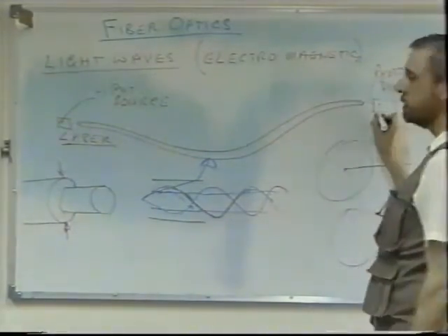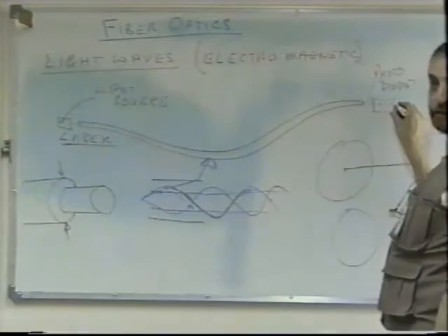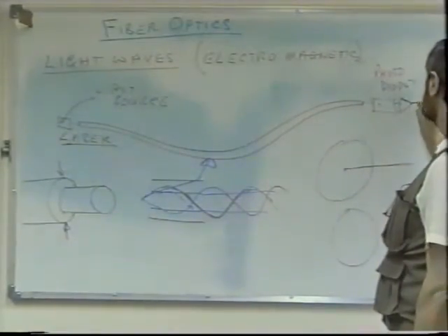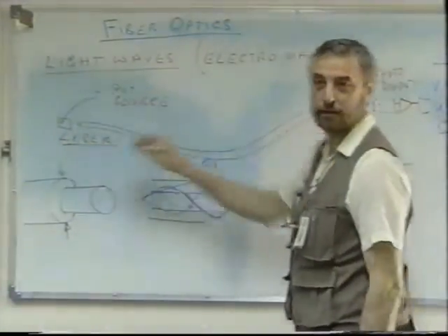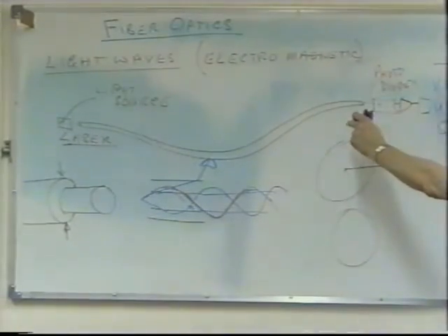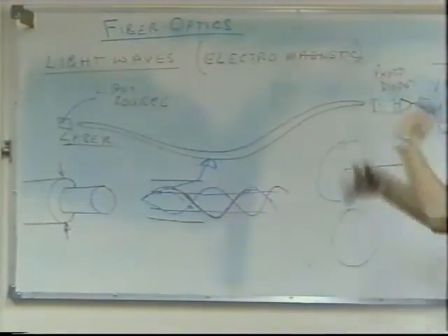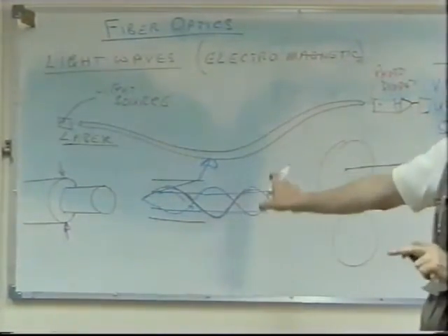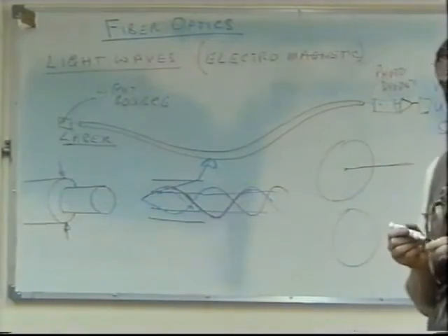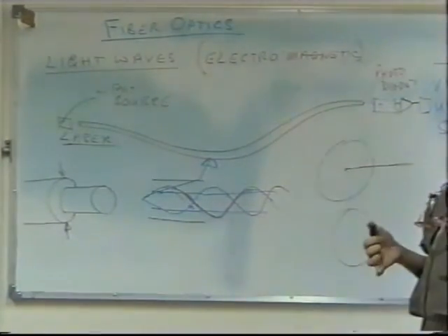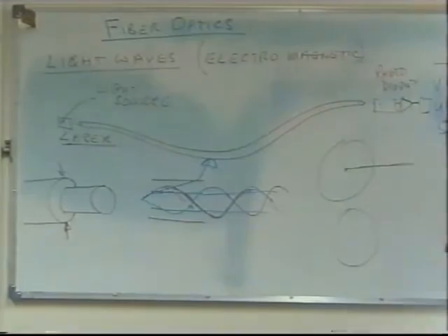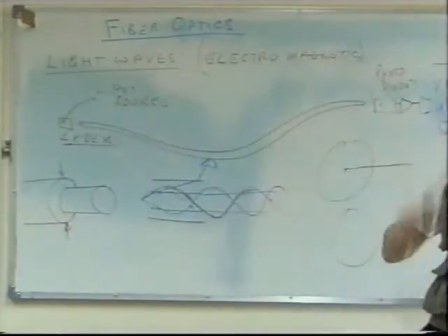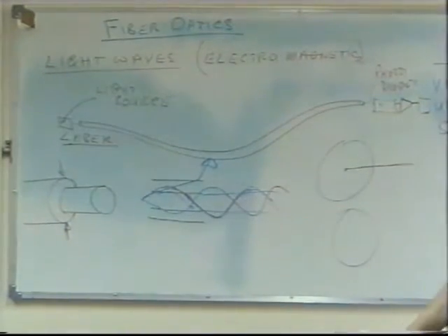Basically, a repeater would be a photodiode, creating, and then a little amplifier, and then another laser for the next section, regenerating your signal. It'll all be digital signals by then, by the way. These are all digital signals, not analog, so they can be regenerated. And when you make your long-distance telephone call now to another city, say to Riyadh, part of your call will be transmitted over these laser links, these optical fiber links.